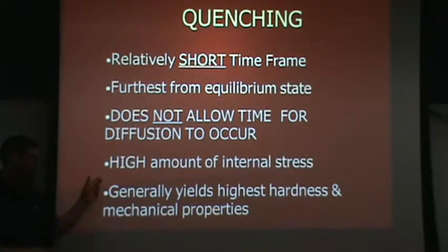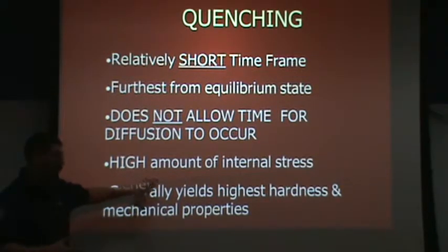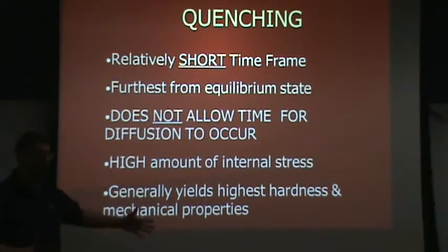The other thing that can be a source of stresses is not only corners, but just big changes in dimension. So if I've got a thick section right next to a thin section, there can be a significant amount of stress developed during quenching between those two. And so you have to see if it's going to be a problem or not. This may or may not be a problem because you've got different alloys that are going to get different microstructures present based on how they're cooled.